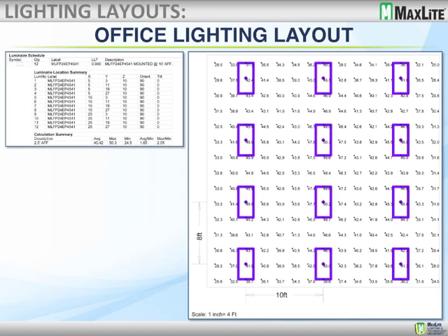Like I say, in office lighting, we'll do an 80-50-20. So if they don't mention it at all, we're going to use the 80-50-20. Correct, especially on an interior office. On a warehouse, we'll use a different one, which is our standard go-to. But there are also ways that we can figure out the reflectance value of a certain surface. It takes a little bit more calculation on our part, but we can get that figured out.